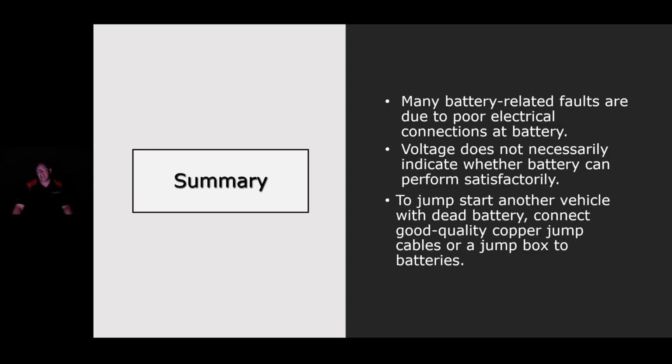Those lithium batteries, when I saw what it was doing, it kind of scared me that, hey, I could have burned my car down, and if it was in my house, in my garage, I could have burned my house down, all because the battery was swelling in the heat. So the lithium battery packs that you carry to charge your phone, that are roughly the size of this hard drive right here, I would say are probably not a good thing to leave in the car in Bakersfield, where temperatures often exceed 80 degrees, 75 degrees, and in the trunk of a car you're looking at 120, 130 degrees. So that's not good, okay?